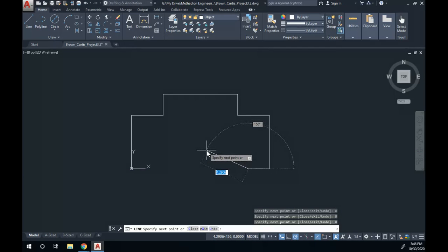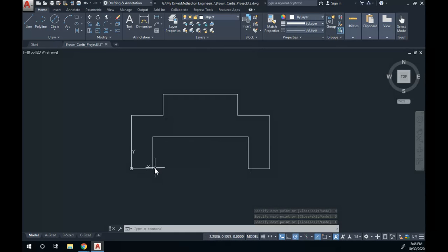All right. Supposed to go up 3, and go over 9, and then go down 3 again. And then instead of finishing it where I started, right click, hit close. It finishes the line command and also finishes the bracket. So it brings that line straight over to the origin. The next piece, it doesn't tell you where you should start it.